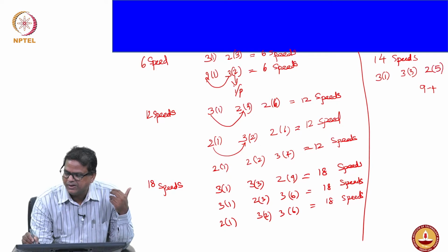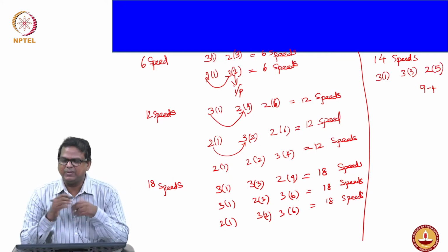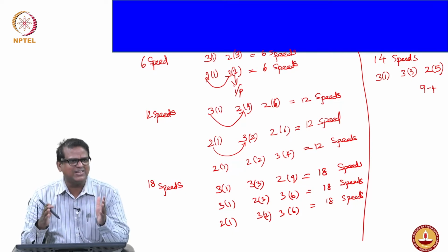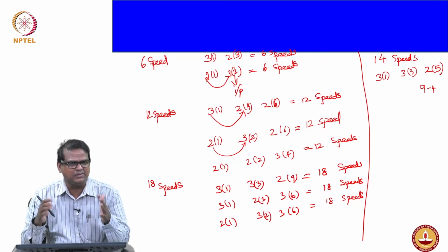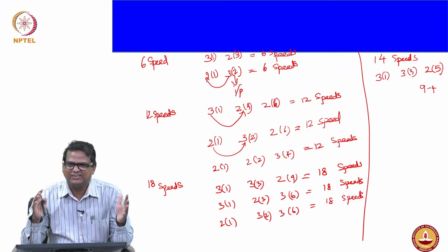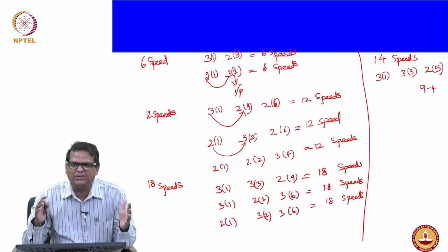So in this way I can arrange. You may ask the question, what happened to the remaining 4? Because the gearbox itself is 18 speed, we can't eliminate them. So instead of elimination, we will give 4 speeds as idler speeds, right. When you have idler speed, what happens to the gear ratio? It will remain the same. That is how we do the arrangement.